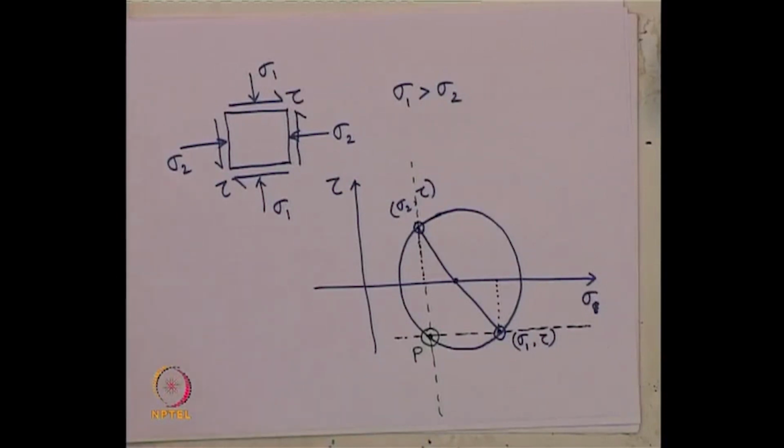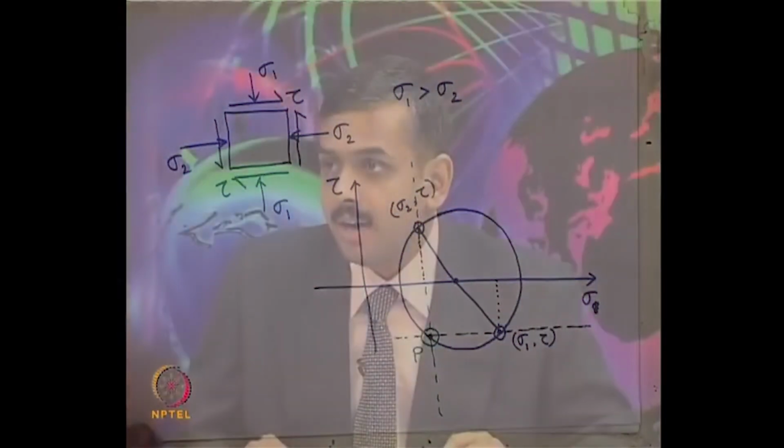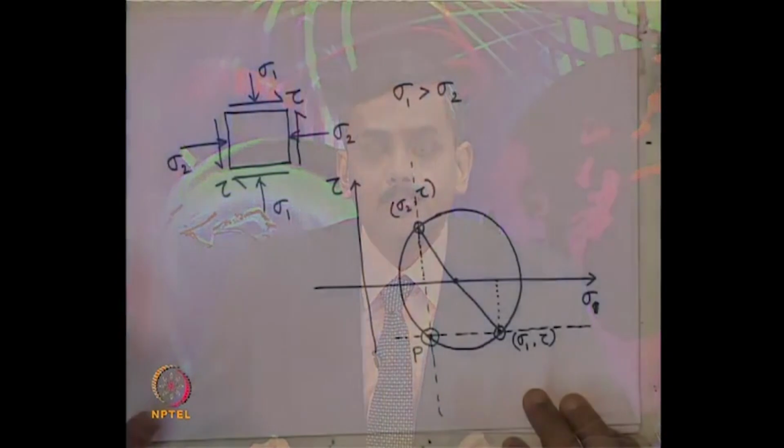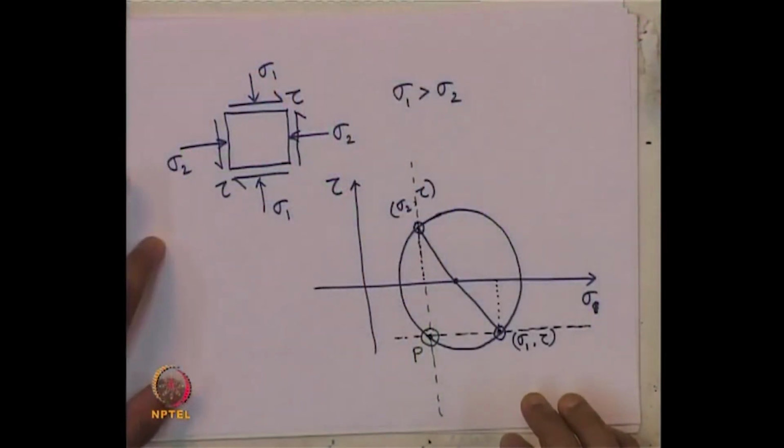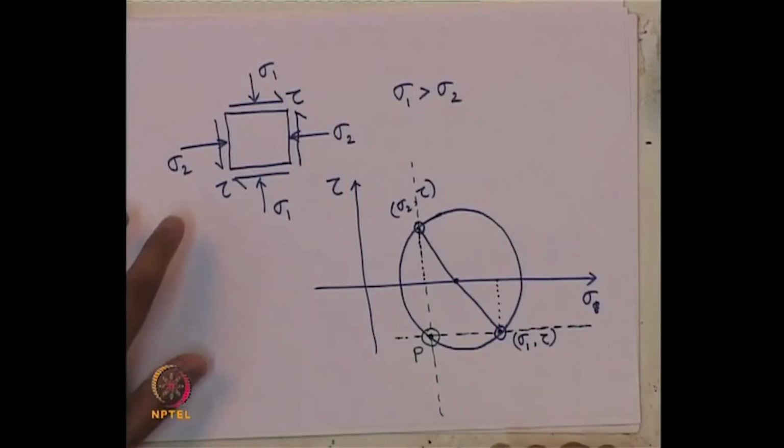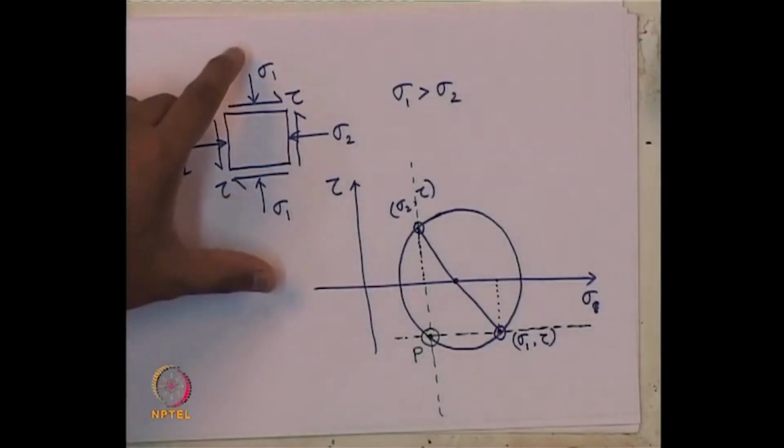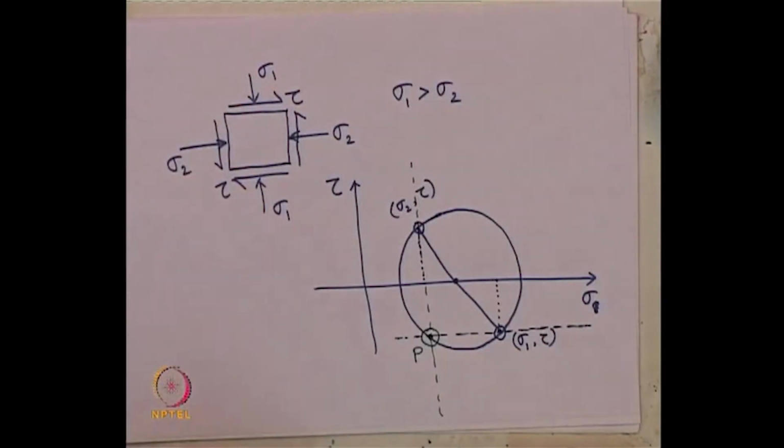So, this is the representation of two dimensional stresses. Considering two dimensional stresses for soil in our static problem is pretty well valid, because when we take any soil element, we consider the vertical stress is one major principal stress and the horizontal stress throughout the cross section remains uniform, we assume in static problems.